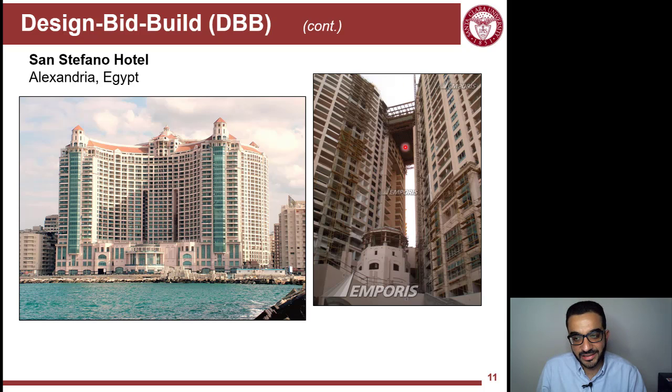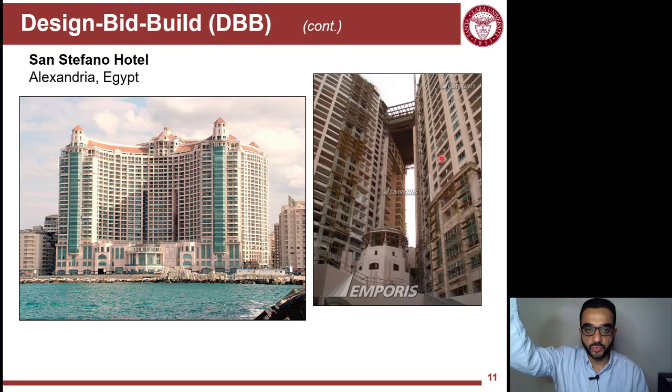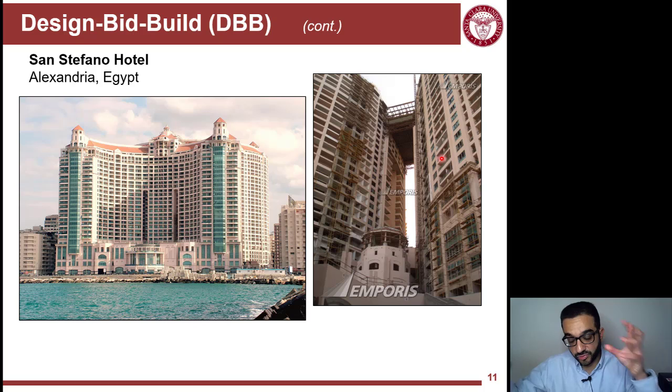The design was fine, but my supervisor told me, can you calculate the weights of the trusses that are used here? When we calculated the weights, we gave these numbers to the contractor. The contractor figured out, I cannot build it. It's so heavy, so high above the ground, that there is no crane able to put this in place as one big bridge. So we had to think about how we could revise the design, cutting it at some splicing joints, so it can be assembled out there with different cranes.